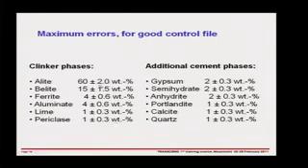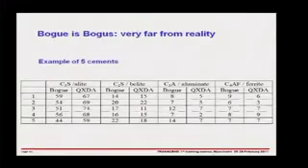So you saw previously, when we were looking at the amount of alite that reacted, we were talking about a measurement of about 60% plus or minus 2%. And this goes back to what I showed you earlier, that for different cements the difference between a correct X-ray diffraction analysis and an estimation, a Bogue estimation, can really be quite large and is not necessarily systematic.